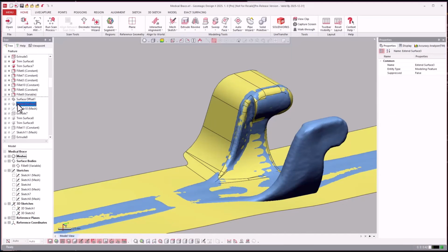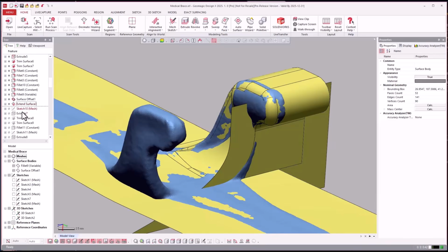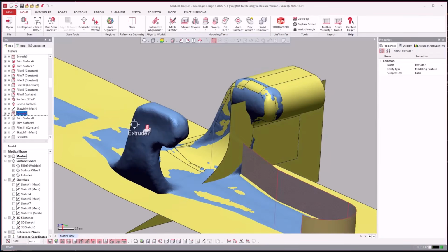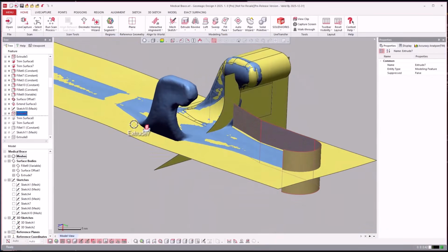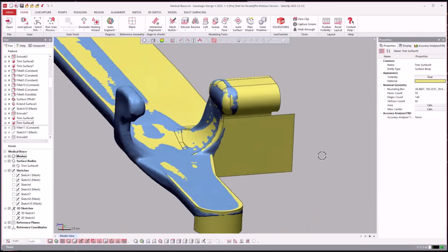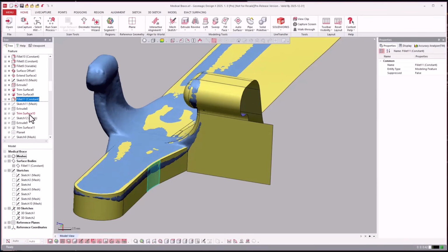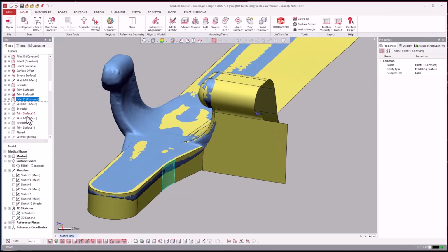If you've done some modeling, trying to fillet things together is hard, because fillets operate different in every single software. So doing these fillets intermittently on final sub-assembly type, it's not the right term, but parts, as you model sections of the model, then kind of come back and you see here, add fillets to it wherever you can. I tend to try to save them to the end as well, but it just depends on the part when you kind of come in and add those.